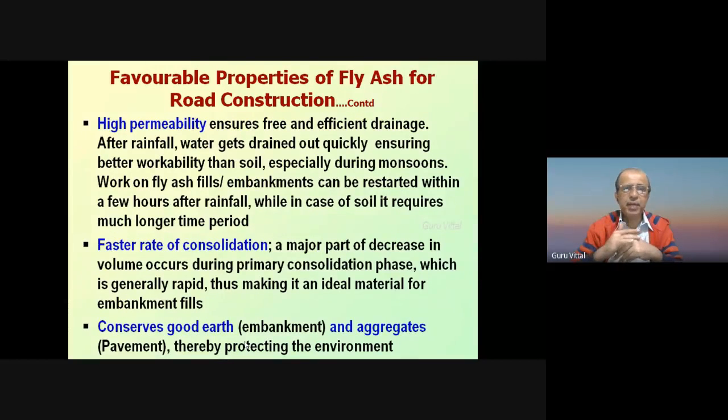High permeability ensures free and efficient drainage after rainfall. The water gets drained out quickly, ensuring better workability than soil. This is especially useful during monsoon season, so the work can restart immediately or within a few hours after rainfall, whereas the soil will require a much longer time.